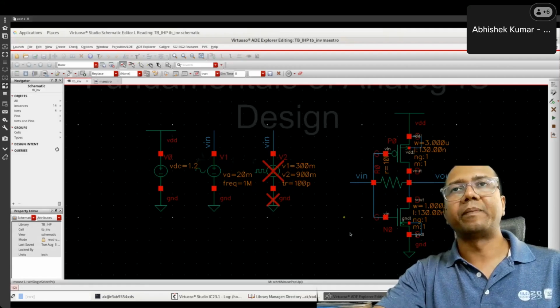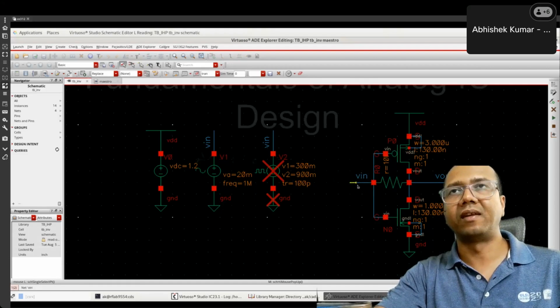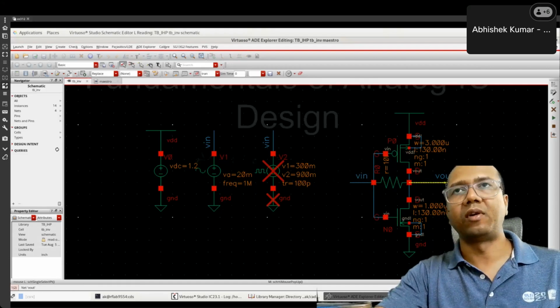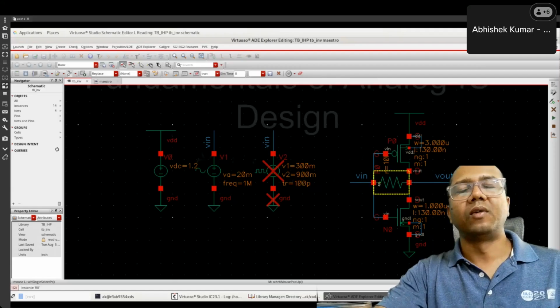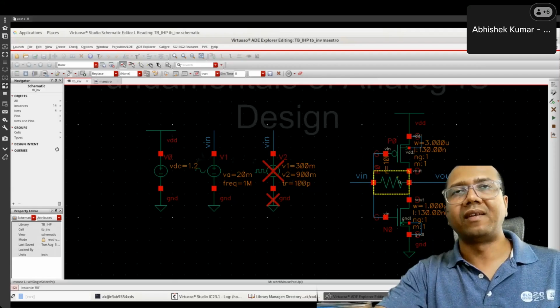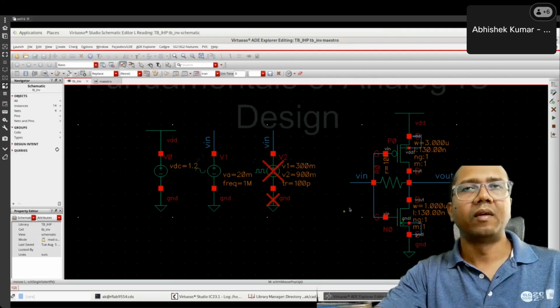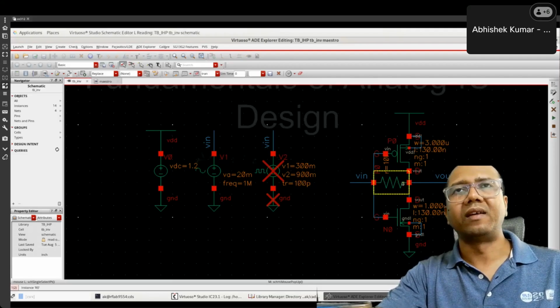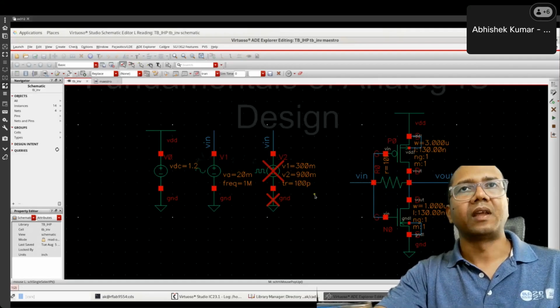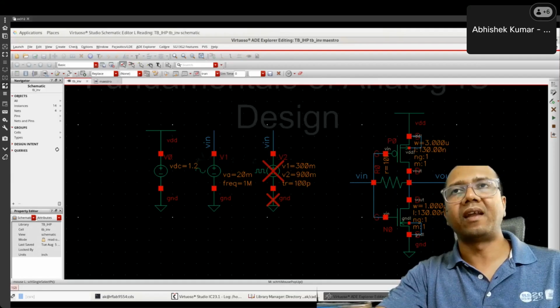So this is a simple circuit where we want to drive this inverter with some input signal, and we want to see how the output looks. I have added this extra resistance here, which is fine if it is not clear to all of you, but this is needed when you want to, let's say, add some kind of biasing to a circuit. And I will show you that the simple circuit can actually also act like an analog block in addition to doing the standard digital processing.